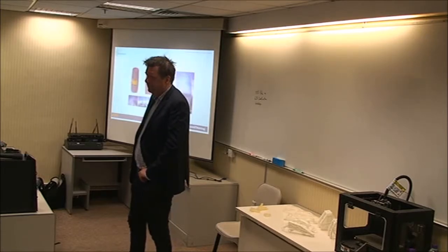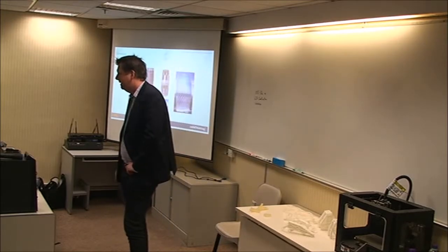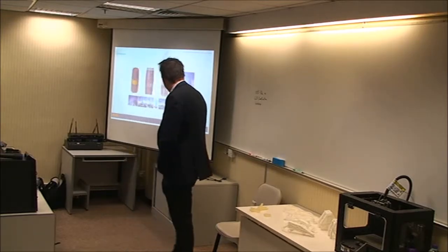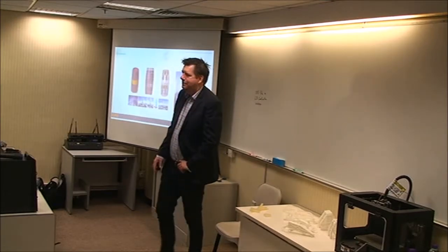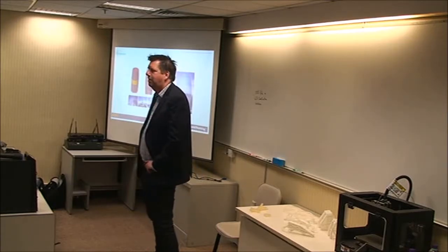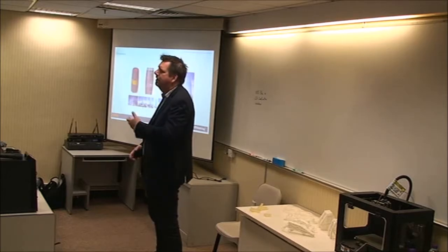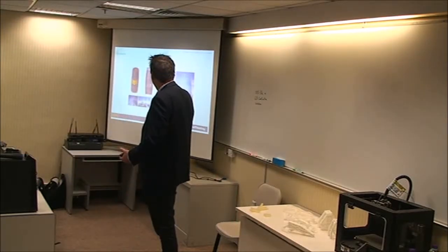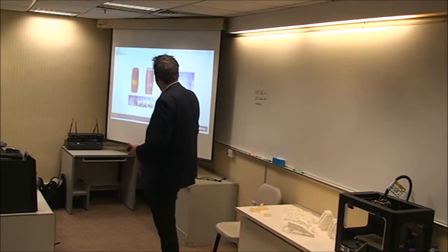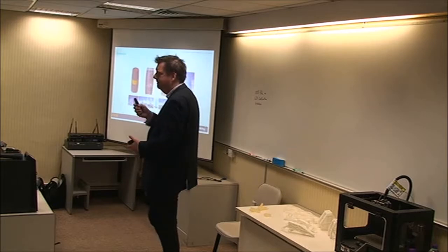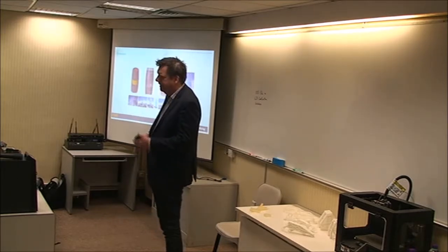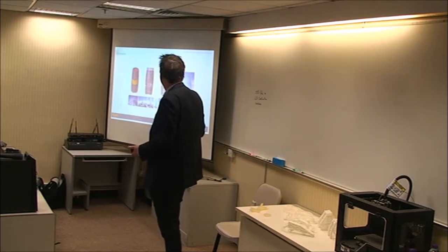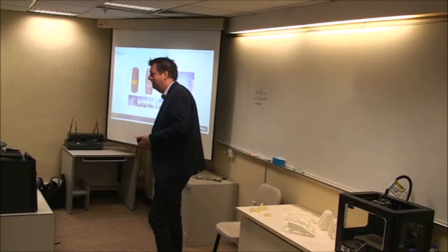Some more architectural stuff. Luca is one of our colleagues. He's been mentioned a few times. I've worked with him on a few projects. He wanted to replicate the type of things you see in some of the nice architectural designs. So I had a crack with Inspire, not trying to duplicate it, but just show its use as a thinking tool. I divided the tower up into the bottom part, the middle part, and the top part. Each one of them, you can just about see the rotational symmetry planes. I had different numbers of symmetrical planes on each layer. I did some wind loading and a pseudo-seismic load on them, and got this very latticey structure. Then I used a few tricks to put a solid structure on the inside to get a decent rendering.